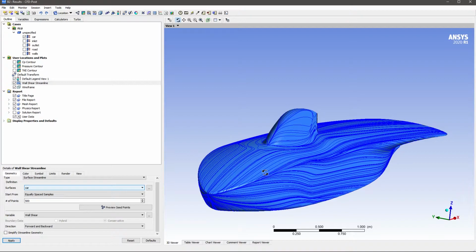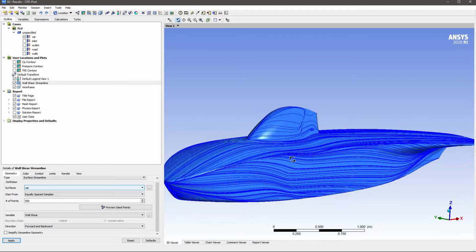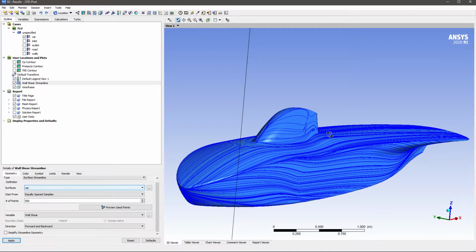it's important that we export the media in order to get everyone able to view it, because CFD-Post Viewer is nice, but it's not as nice as the post-processing images that can come out of it. So we export our media as images. CFD-Post gives you the option to do animations, but they're not particularly useful, as the static analyses are preferable. So in our case, it is important that we get images of all the important parts of the car.